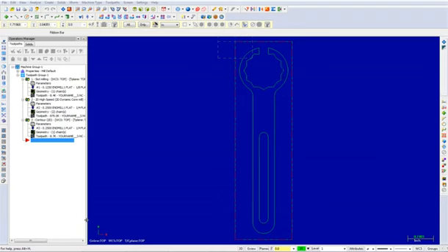In this video, we will clean the inside shape using 2D high-speed dynamic contour. 2D high-speed dynamic contour toolpath utilizes the entire flute length of the cutting tools and is used to mill material off walls. It does support both closed or open chains. Select Toolpaths, 2D high-speed, dynamic contour.